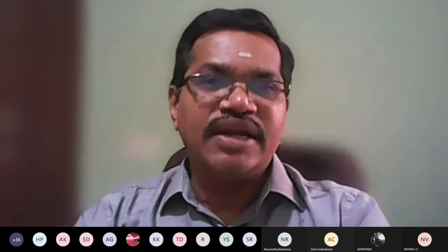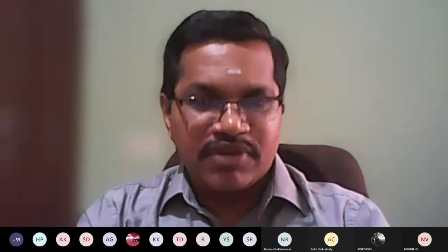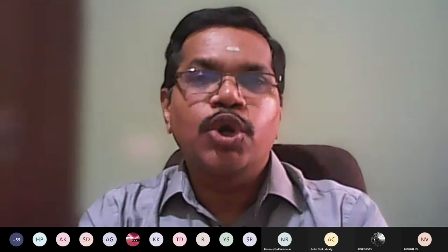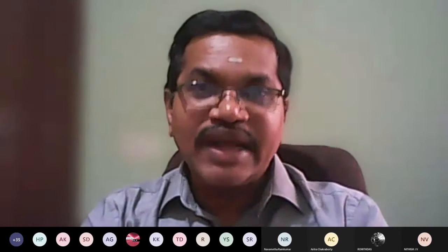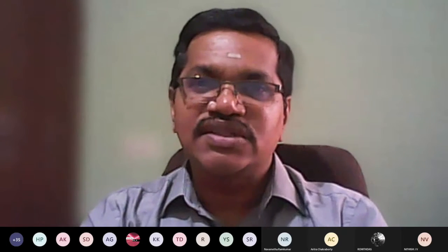The second time duration is required for establishing the depletion layer. The depletion layer should grow in thickness. For that, the applied reverse bias will need some time for the depletion layer to grow in thickness. That will be the second time duration. Now, during both these time durations, that is carrier sweep out or removal of excess charge carriers and the growth of the depletion layer, the voltage across the diode will not change drastically. It will be very close to that forward voltage drop, as long as there are charge carriers in the n-minus drift region.